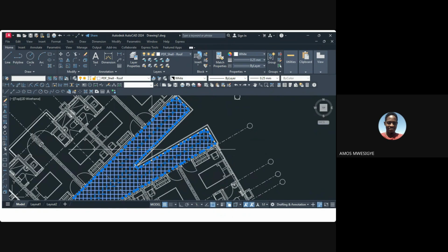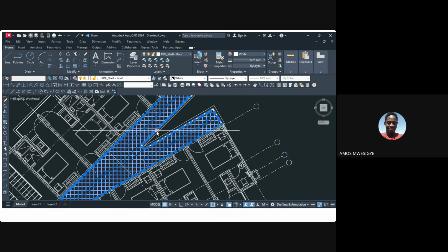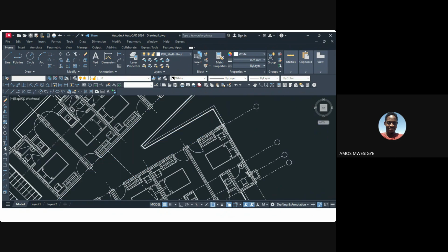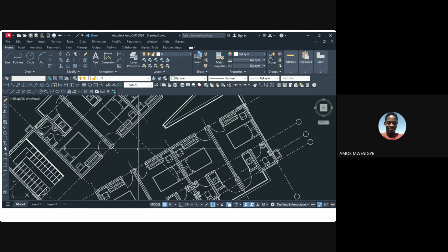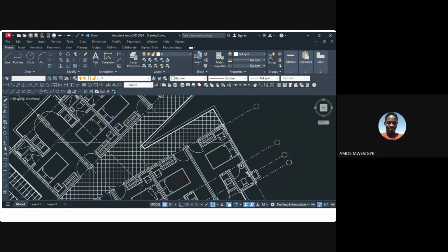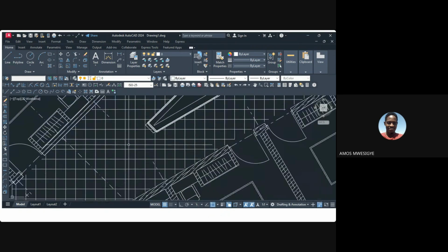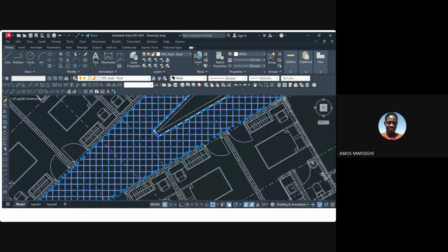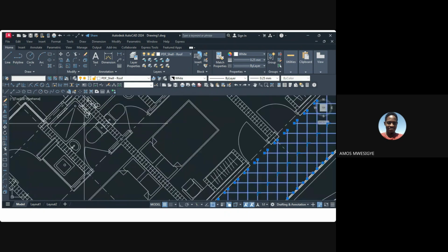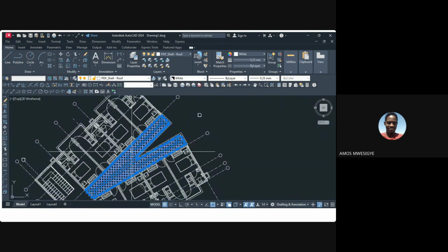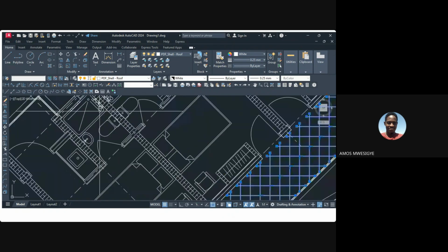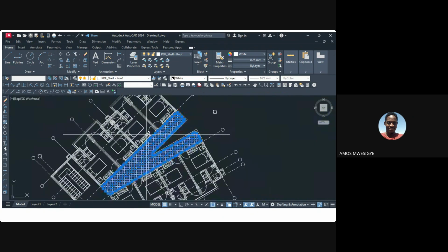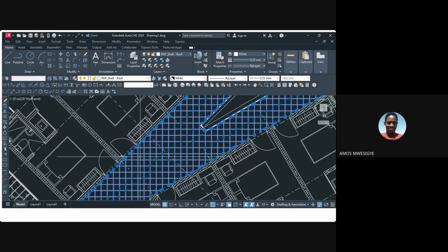The flow type. So I can select that and delete it. You make sure if you select similar, you see. Let me show you again. Because there are some PDFs, you're going to select this here, and when you select the similar here, it might also highlight maybe the toilet, which you don't want to delete because you're going to show a pipe here, the drainage from the toilet. So you don't really want to delete that.